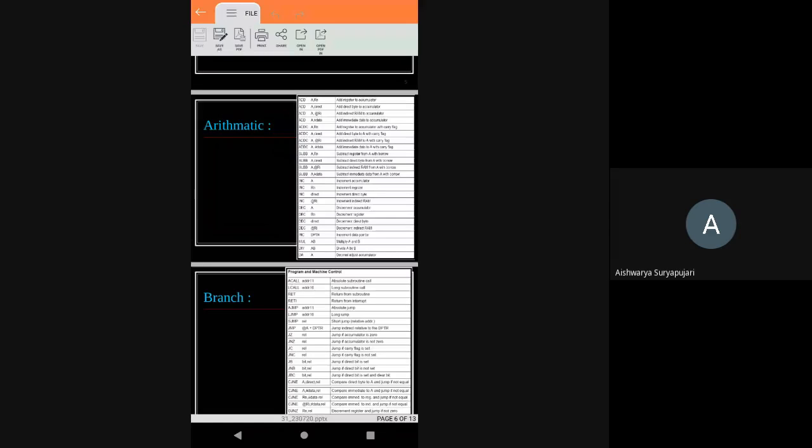So any value we can put here and the instruction will become, this is the syntax they have given. And it's a description. So if you are putting n is equal to 1, the instruction will become add A R1. Add A R1. So what is the meaning of that? So definitely the add stands for the addition, arithmetic operation. So what it is doing? It will add the value stored in R1 register.